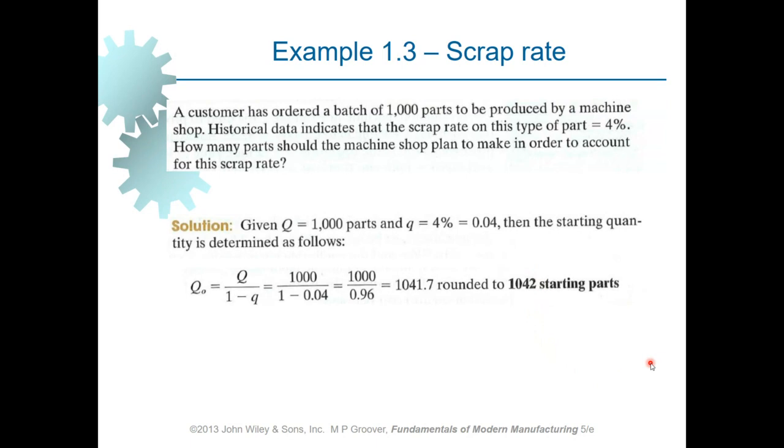Well, technology is not perfect, skill level is not perfect, materials are not perfect, machine tools are not perfect, and these are the reasons why there is always a non-zero scrap rate. Sometimes in the problems, it is mentioned that scrap rate is zero, but in reality, it doesn't happen. Always there is a scrap rate. It could be very small, but it is not zero. If we want to make it zero, it means that we've got to reach perfection in everything, and that is not really possible. That's not practical.